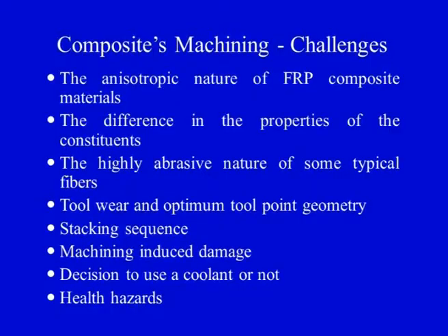So, that has to be taken into account while we are selecting the tool material which would be used for the machining operation, because if the fibers are abrasive in nature, they will abrade the tool material and the tool wear would be very high, and the tools have to be replaced at regular intervals of time. So, that we do not want, we want to have a longer tool life. Therefore, the highly abrasive nature of the typical fibers may also be a challenge when we are trying to machine a composite material which has been reinforced with abrasive fibers.